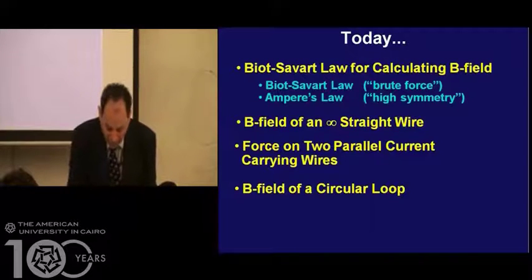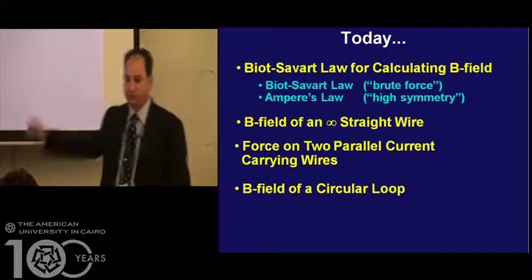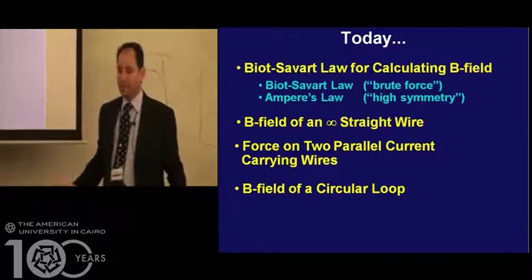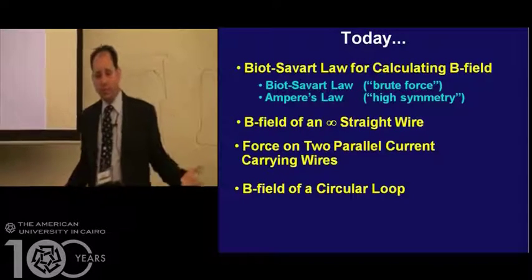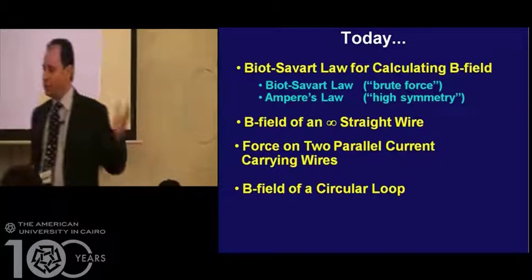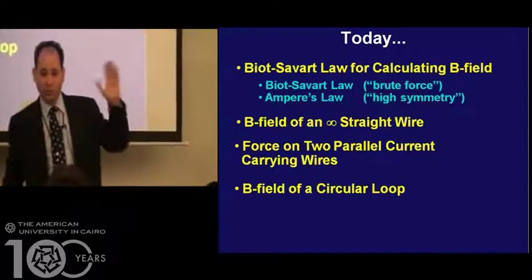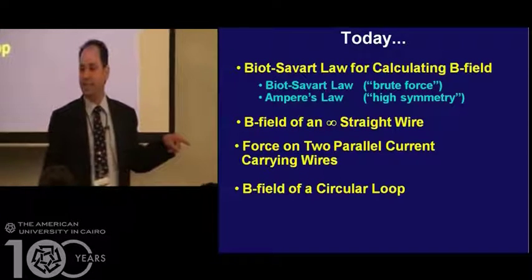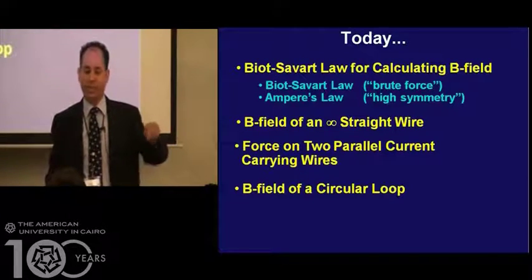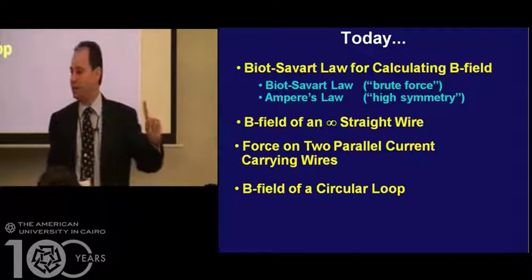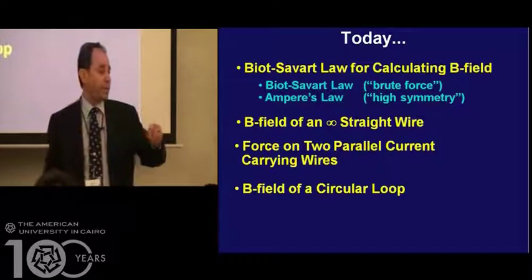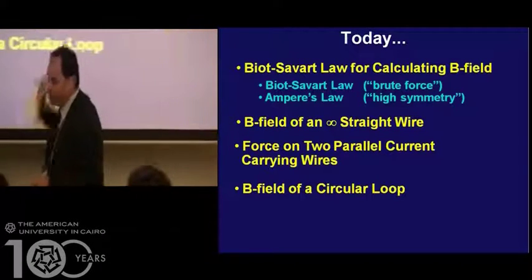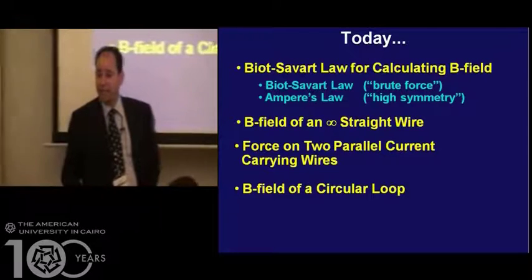Now we're saying that if you have a wire that carries a current, then around that wire there will be a magnetic field. And we all notice that when you walk in the street and go over a high power cable which has a current, you hear noise in your radio. This is because of the interference between the magnetic field produced by that wire and your antenna, and that produces noise. Now we're very interested in calculating the magnetic field from these wires.